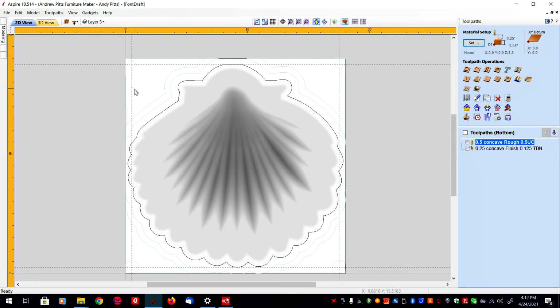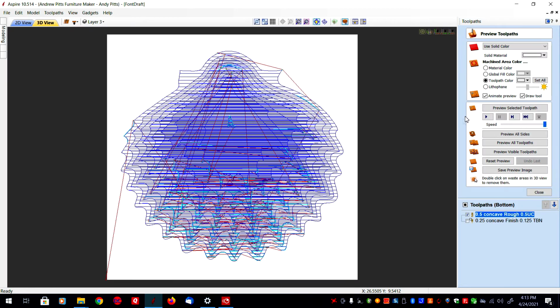So the screw head was 3/4 of an inch into the material, which means that the threads went 3/4 of an inch into my spoil board. I did that on both sides since I was going to be flipping this top for bottom. As long as I put these screws 1/2 inch in from each corner, it should flip and give me reasonable accuracy. So the first cut was, let me go ahead and bring up the 3D.